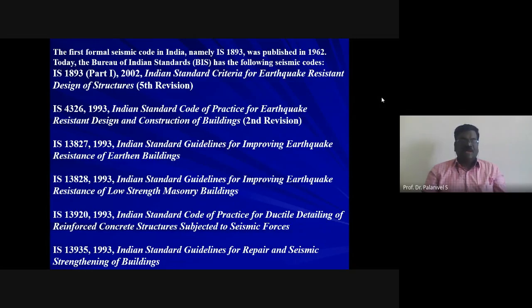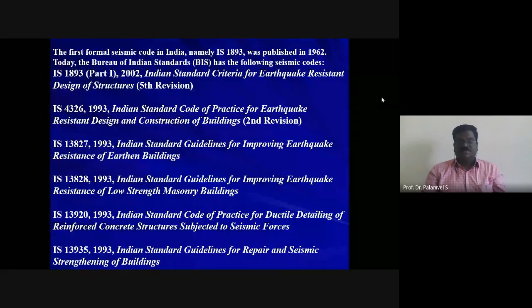As I told you last class: IS 4326 1993, earthquake resistant design and construction of buildings. IS 13827 1993, Indian standard guidelines for improving earthquake resistance of earthen buildings. IS 13828 1993, guidelines for improving earthquake resistance of low strength masonry buildings. And IS 13920 1993, recently revised in 2016, the Indian standard code of practice for ductility detailing of reinforced concrete structures subject to seismic forces.